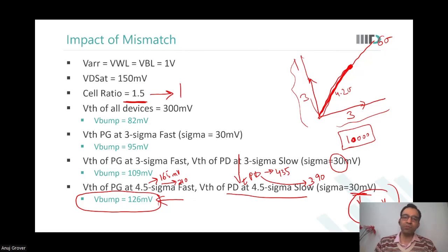Then you can do that. But if you're working at ARM or at Synopsys, you cannot really request a specific SPICE card for a memory cell with a cell ratio of 1 that has reduced variation models inside it. You cannot do this design.